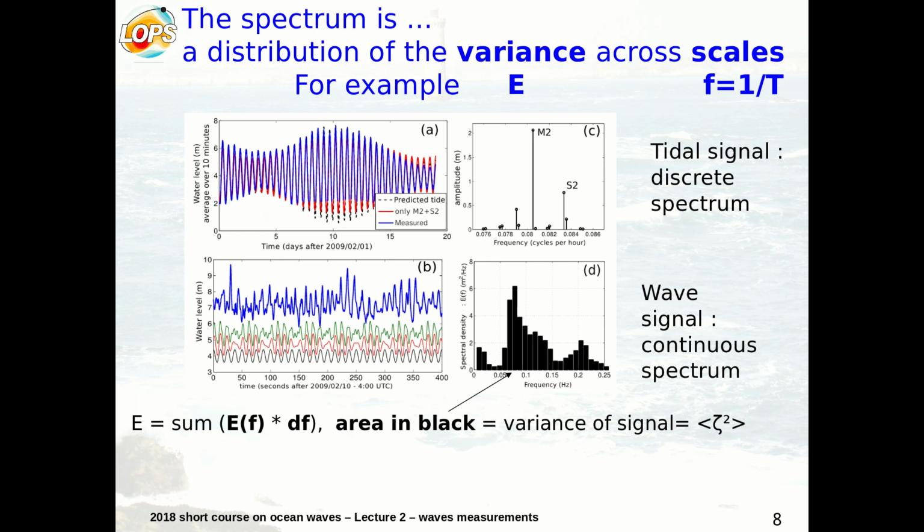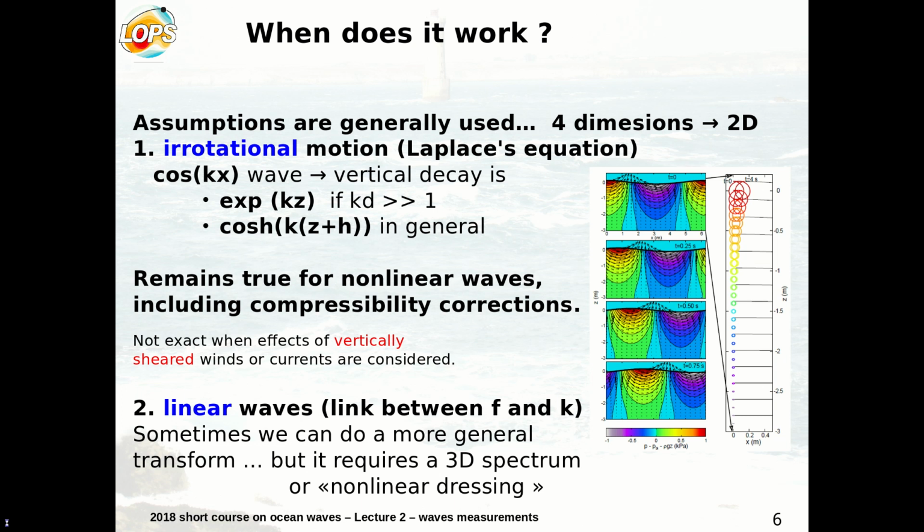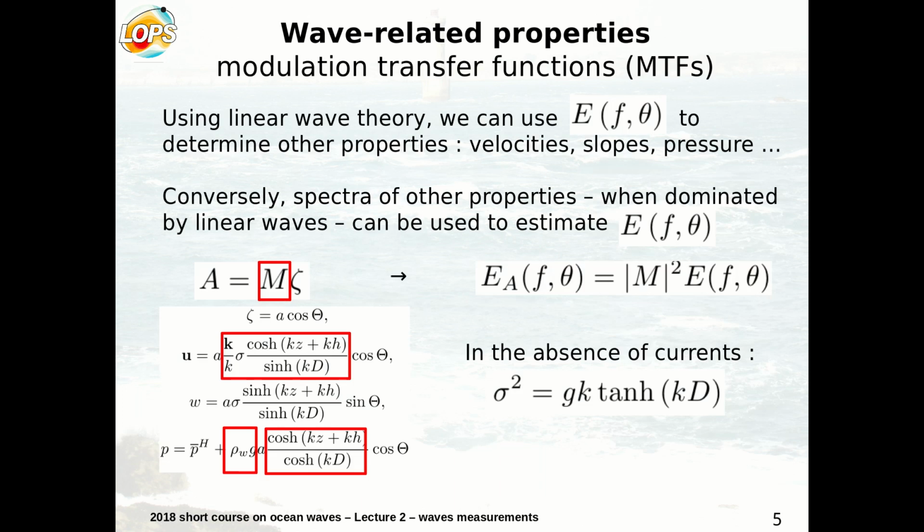We measured this kind of time series of pressure, and from the pressure you can convert to the surface elevation, applying what I was showing just before. The pressure is some coefficient times the amplitude of the surface elevation. So essentially you have this coefficient here, which transforms the surface elevation to the bottom pressure.